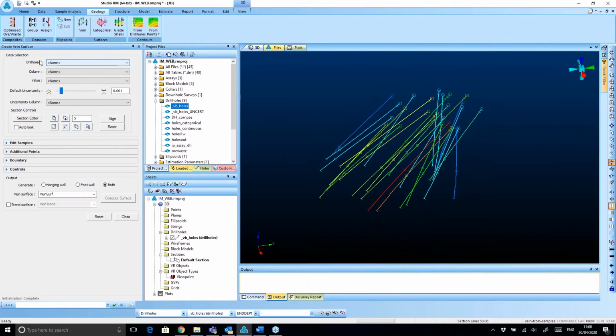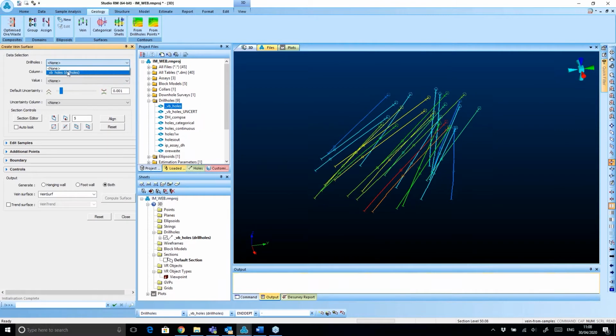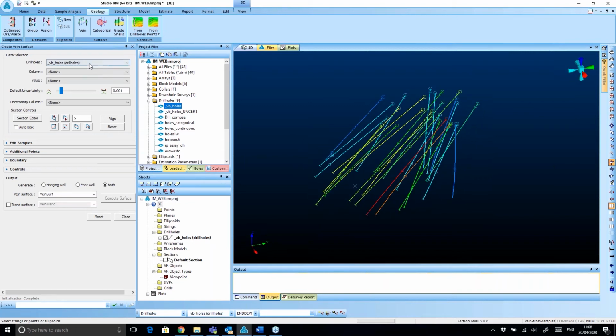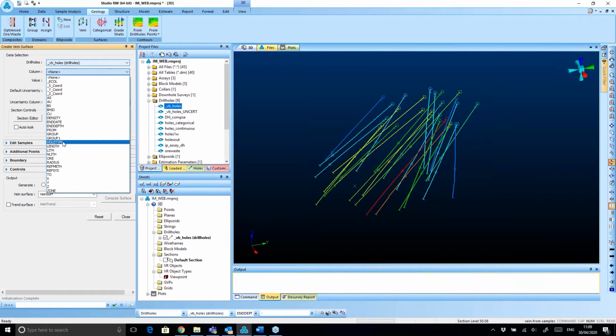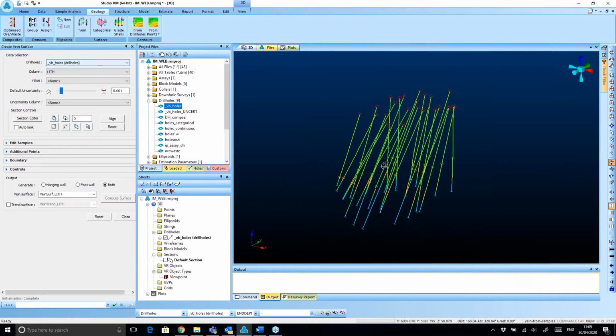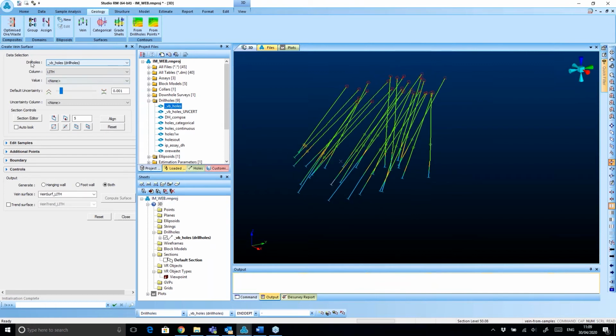Yeah, then after that, we have a data selection here. Then let's select the data: VB holes, my drill holes. Then if I go to here, I can select my lithology. And then the system automatically recognizes the lithology codes that I have in my drill hole file, right?